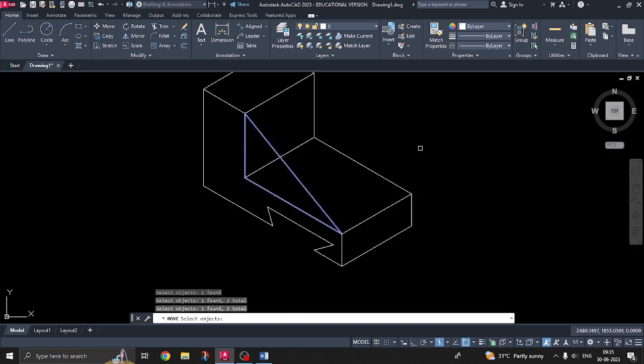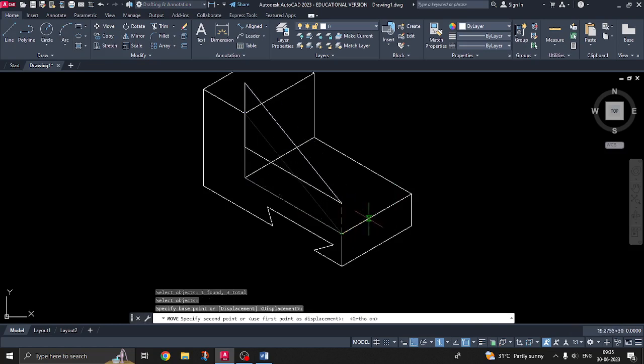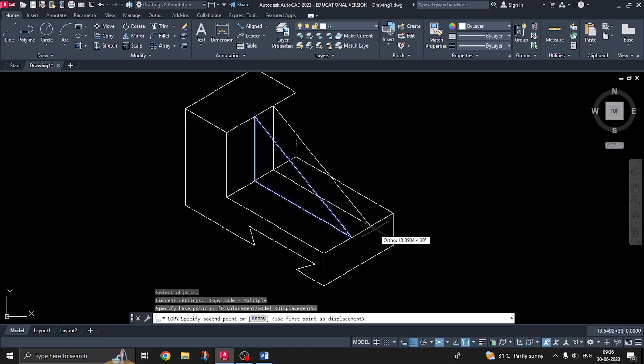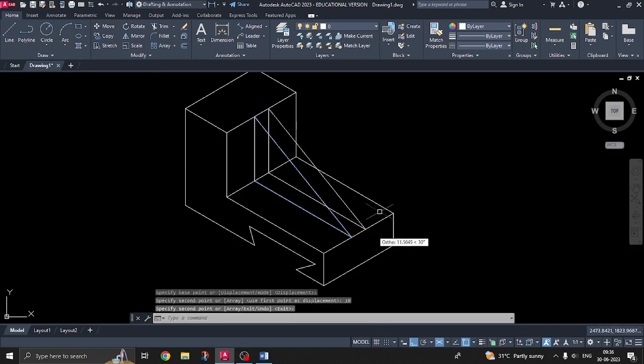draw the line along with the corners, and then let us move it. 1, 2, 3, enter, and this corner as a base point, move it, switch on ortho and F5, isoplane. We are going to move this way, so I switched on the isoplane. F5, 20, 20. Okay, thereafter copy this triangle, same triangle, from here 10 mm. Okay, then trim the unwanted portions. Whatever is not visible, those lines you have to trim carefully. Okay, done.